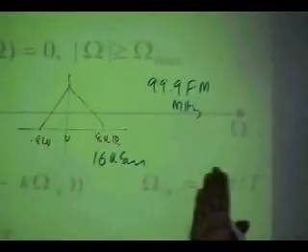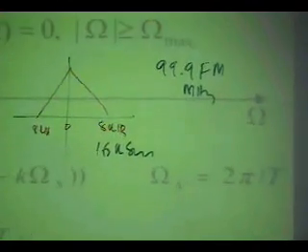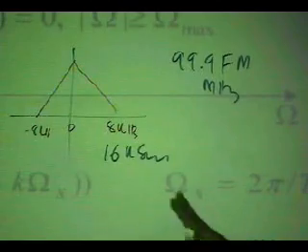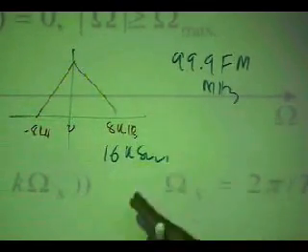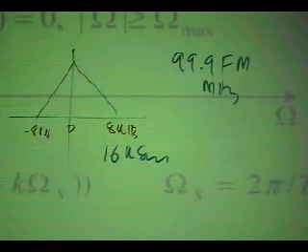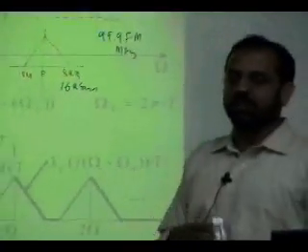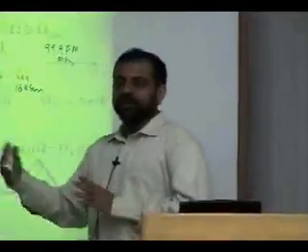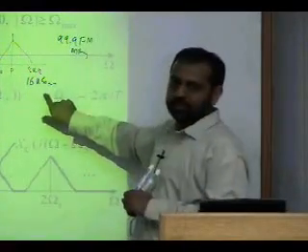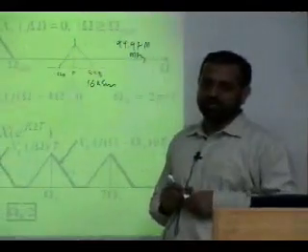Just taking this voice from voice to a band requires a lot more samples. Okay, so you are still having more than 16 kilo samples per second, but not 200 mega samples per second. So this is the trick, that actually you don't require so many samples. And this is what we will spend more time on learning, that you keep throwing away samples, because ultimately you want to come down to this, and this is what you actually play in the speaker. Only 16,000 samples every second.